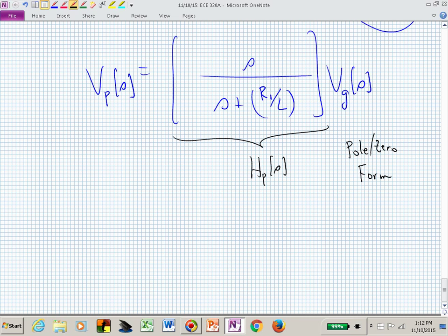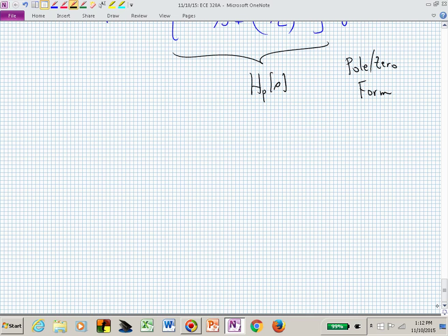This is a high pass behavior. And if we wanted to sketch this, that S in the numerator actually says in a dB scale, the reason we're doing dB is because now we have all these straight lines. We never get to 0. That just keeps going to more and more negative dB. Minus 20 dB, minus 40, minus 60, minus 80. Gets really, really small, but we never get to 0 on a logarithmic scale or in a dB scale.